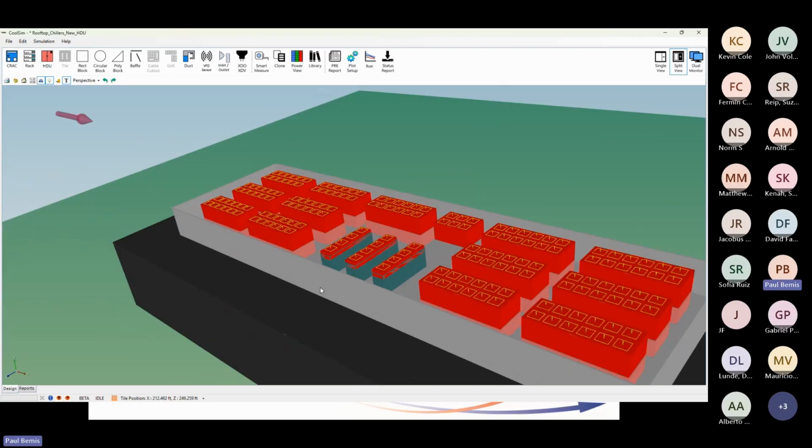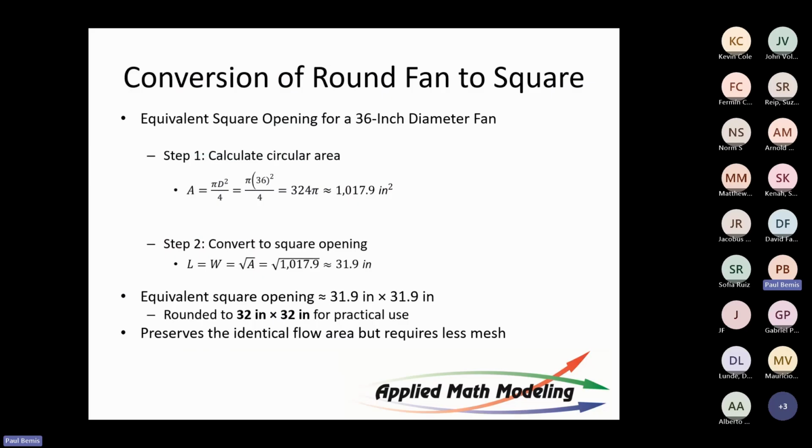So it's the non-solid surface that we're calculating. And that mesh makes a difference in terms of computation time. If I were to make them round, the computation time would go up. So in CFD, we try to be conservative about, or sensitive to, computation time. And so rectilinear structures are often used instead of round structures to save time and to give you approximately the same answer. So all I did here is to show you how we do that.